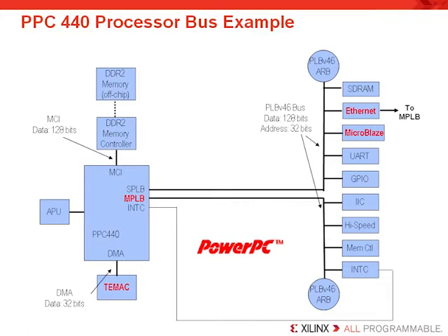Now, this is a little confusing because we're used to having a master PLB bus be a bunch of masters, while here it is a pure slave peripheral bus with no master peripherals, as you can see from this diagram. The slave PLB bus does not allow the PowerPC 440 to access any of the peripherals on its bus, and frankly, most typically, customers don't put any slave peripherals on that bus, except in this case they did. It is possible, but not necessarily likely. Now, this is unusual because we're used to having the processor be the master of its entire domain, but in this case, that's simply put not the case.